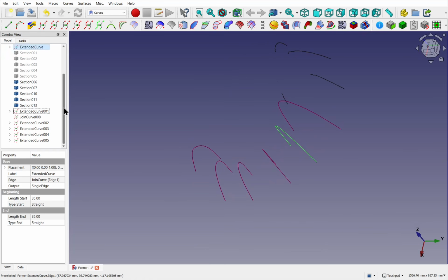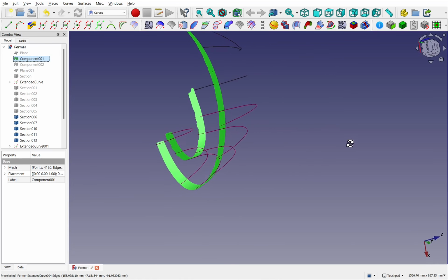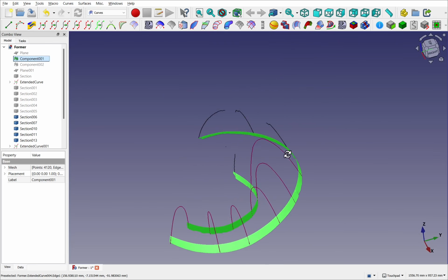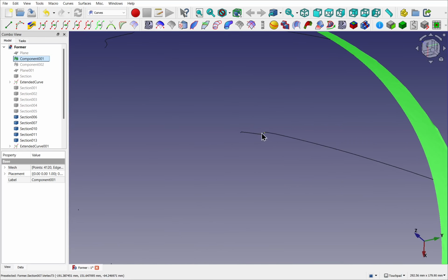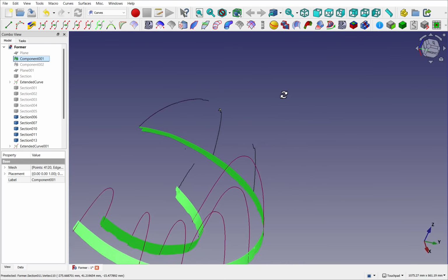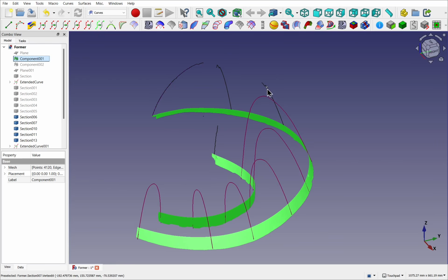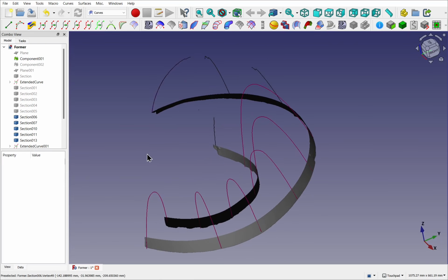And if we look back at the component, bottom part, they're fitting all nicely around there. And we've just got to deal with these now. So these ones are a bit different because we've got some anomalies on here. So we may have to downgrade these, remove these parts, it's all part of that cross sections, and then perhaps change this one to a curve extend, and then change this one to a join curve, because this one's okay. Well, actually we need a curve extend to go down here, so they still need to be curve extends.